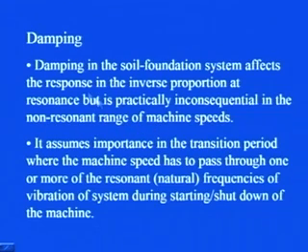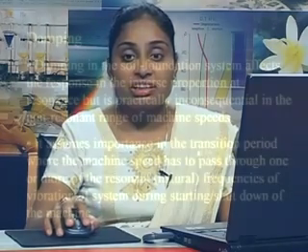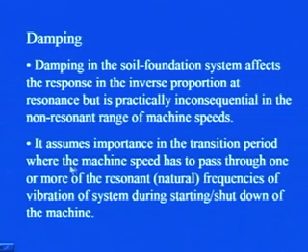So, we have to really see that during resonance, when the amplitude becomes almost infinite, the damping effect is in inverse proportion. It assumes importance in the transition period where the machine speed has to pass through one or more of the resonant or natural frequencies of vibration of the system during starting or shutting down the machine.